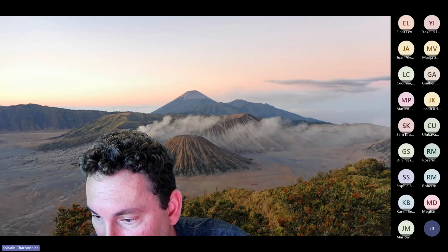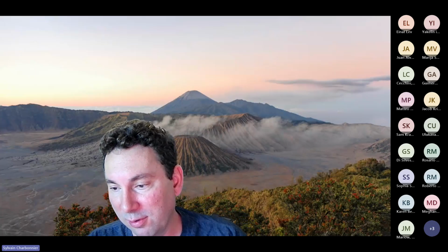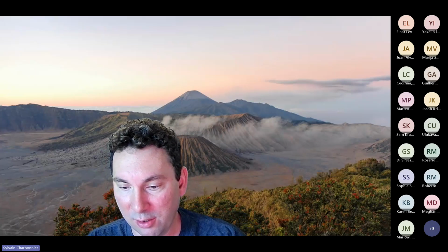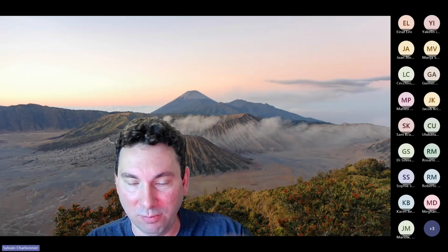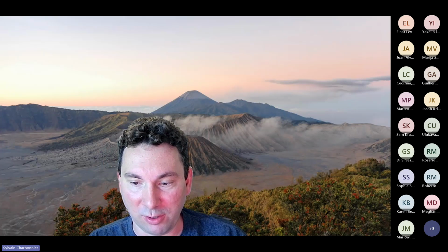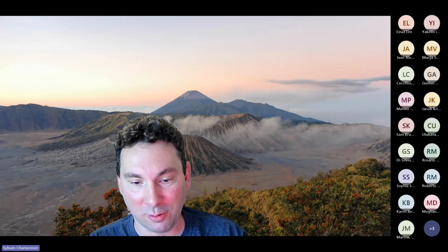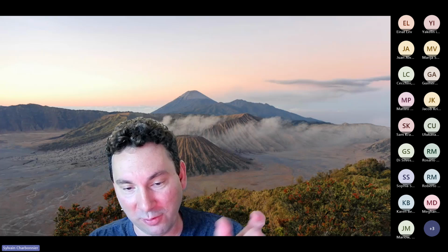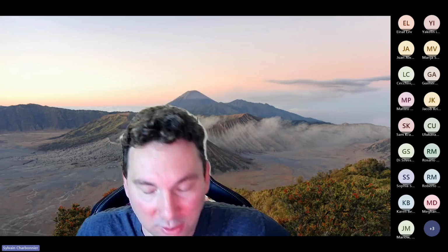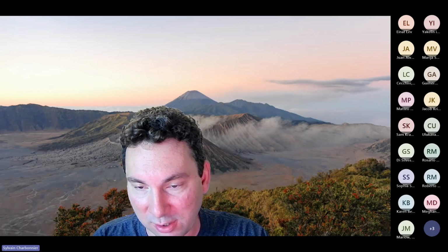So it's okay to use all these digits for the coordinates. Well, you don't have to use them all. Try to use at least, I would say, 3 or 4 after the decimal to make sure that you're precise enough, especially because it's only one building, right? So it's a pretty tiny point over the whole grid area. So you want to make sure that you put enough decimals to actually get that location precisely.